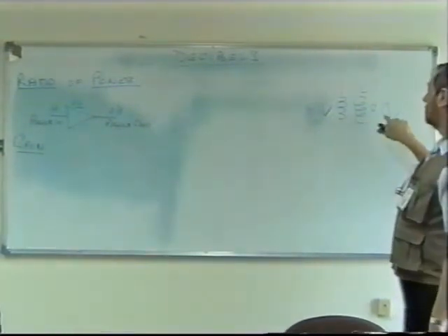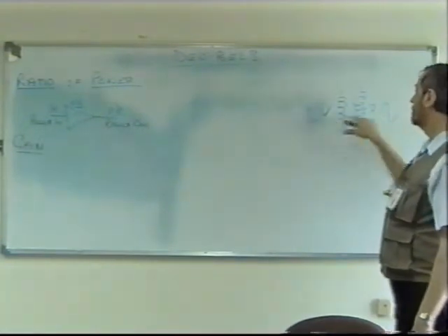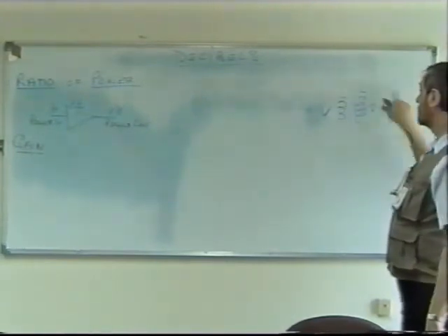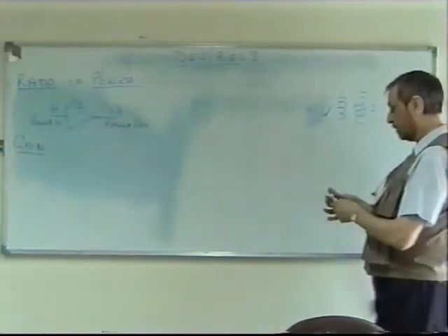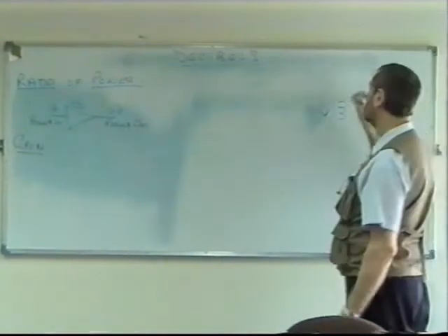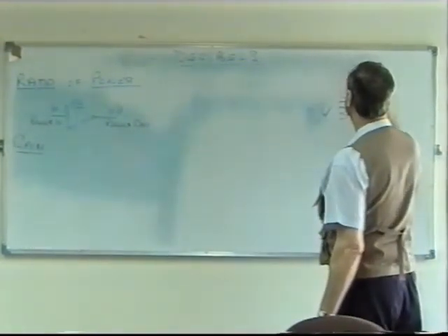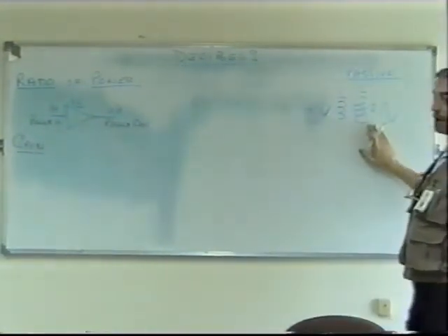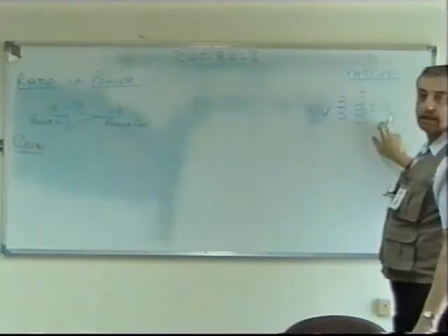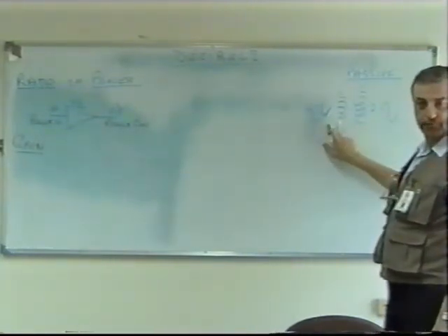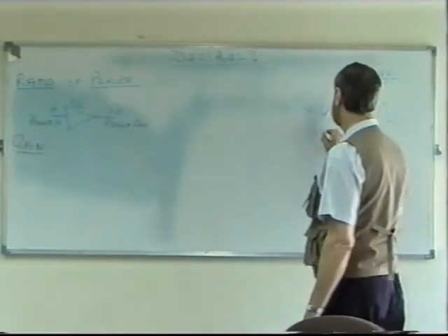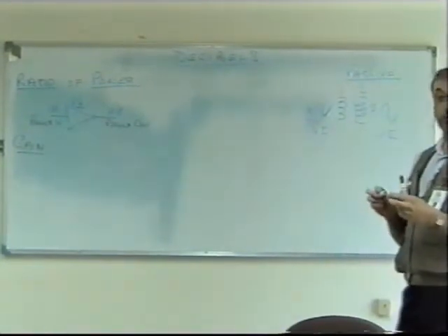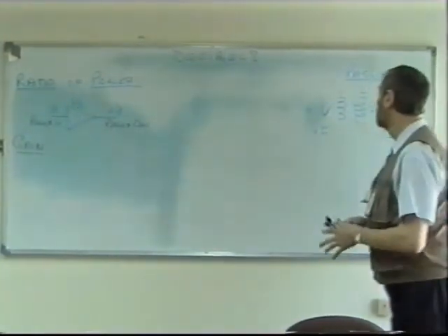Because all I've said here is I've got 1 volt in, what's the voltage out? Okay, it's going to be 2 volts peak to peak. But we must understand that a transformer is a passive device, isn't it? And that's really what we're talking about here. Because it's passive, no power is being added, so we know that the current at the output must be half the current at the input. Because VI, the power input, must equal the VI output, apart from a little loss in the transformer itself.